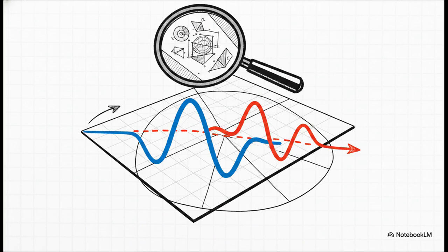And there's a fantastic little quirk here. In standard math, imaginary numbers use the letter i, but in the AC language, electrical engineers use the letter j. Why? Just to avoid mixing it up with our old friend electrical current, which already owns the letter I. By using j, engineers can calculate rectangular, polar, and exponential forms to perfectly track how voltage and current start shifting out of phase with each other over time.